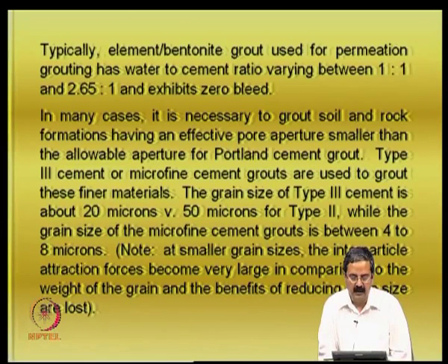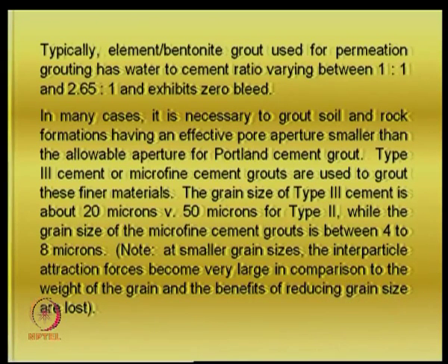We do not prefer too fine a size, because at very small grain sizes the interparticle attraction forces become very large in comparison to the weight of the grain, and the benefits of reducing grain size are lost.